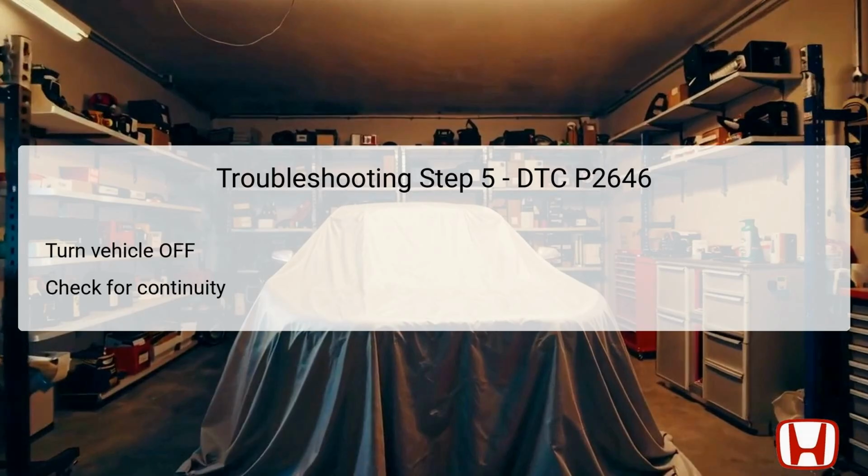Conversely, if there's no continuity, this could suggest that the wiring is intact, prompting the technician to refer to any authorized service information regarding the specific DTCs or symptoms, or to substitute a known good PCM to see if that resolves the DTC P2646 issue.